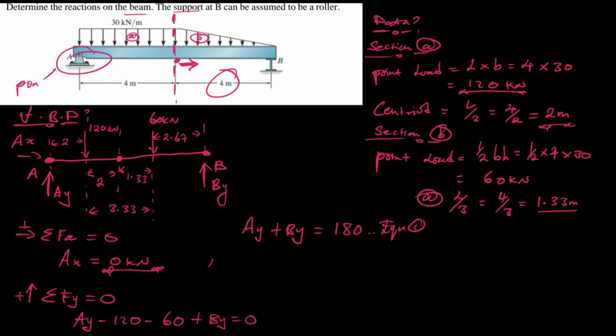Once you have this equation, remember, global equilibrium check doesn't just involve forces, it also involves moments. So now we sum the moments, taking the moment at the point where we have a lot of reactions, which is at support A. So sum of all moments at A, taking this sense to be positive, should give us what? 0. Remember, engineers have the best moment. So let's try and find them.